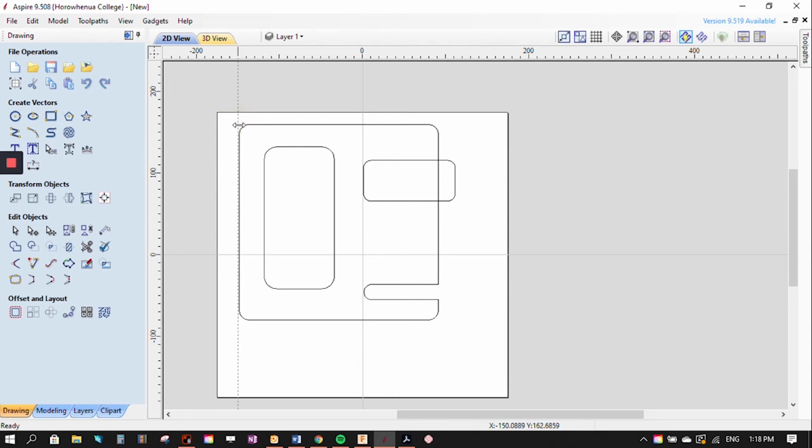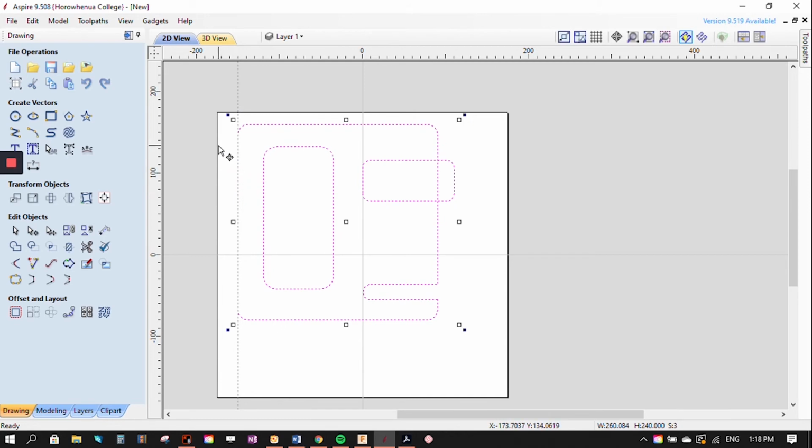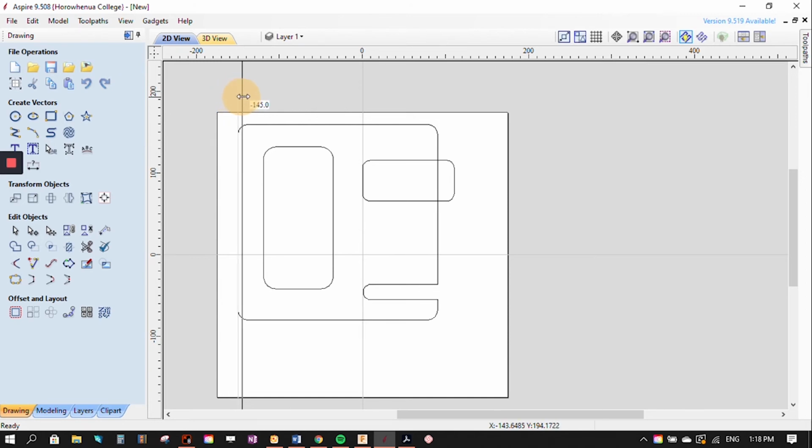It'll sit this line here at 150 millimeters. So what I'm going to do is select the entire section here. I'm going to move it all across, and I'm going to move it back, right? So I've just moved the entire work, so the edge of it is set up to precisely line up with this guide here at 150 millimeters, or negative 150. So that's negative 140, which means it's 10 mil inside, and this is negative 130, which means it's 20 mil inside.